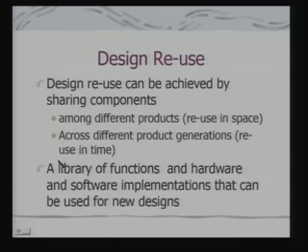So, effectively if I have a platform which talks about a parameterized hardware along with a set of APIs defined on top of that, and if we know different kinds of functions have been implemented on this platform, and if we have them in a library, then for a new design, I can simply pick up those functions and use them in the design.